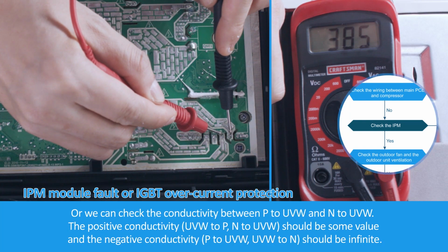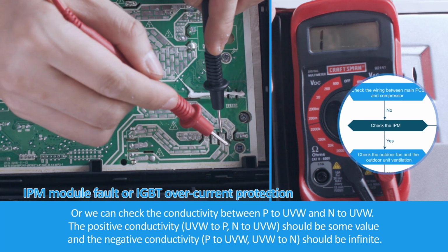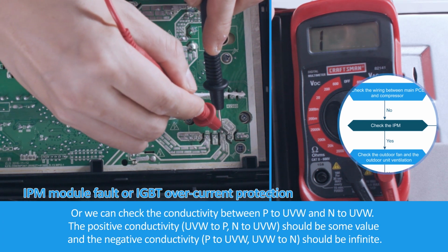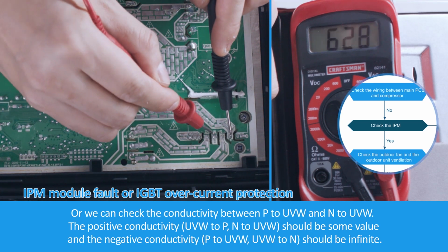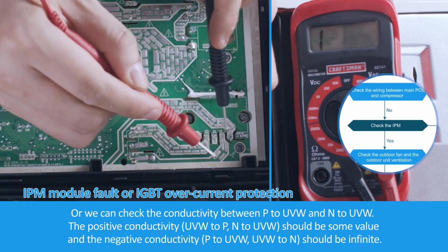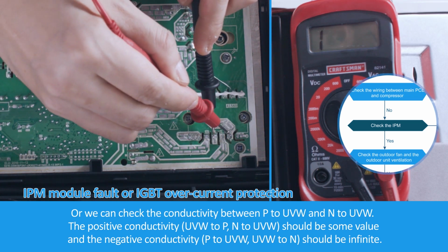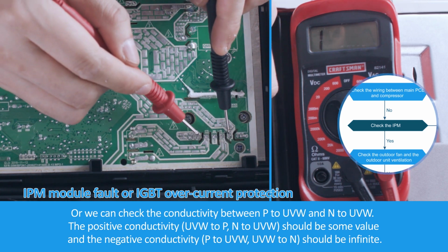Or we can check the conductivity between P to UVW and N to UVW. The positive conductivity, UVW to P and N to UVW, should show some value, and the negative conductivity, P to UVW and UVW to N, should be infinite.